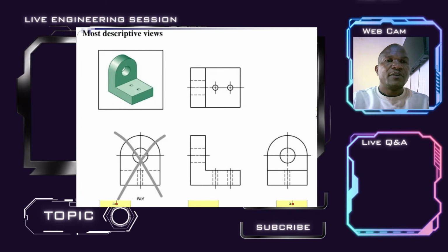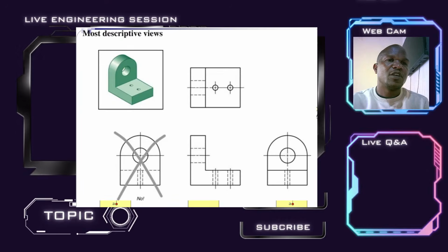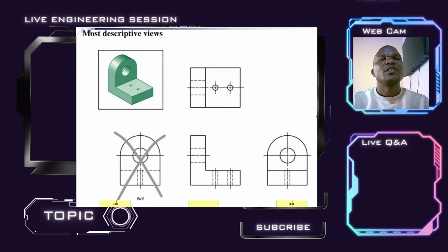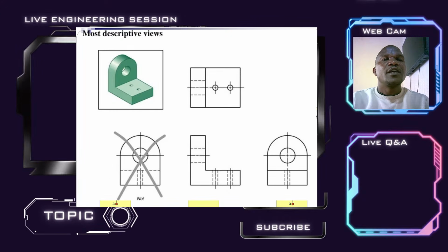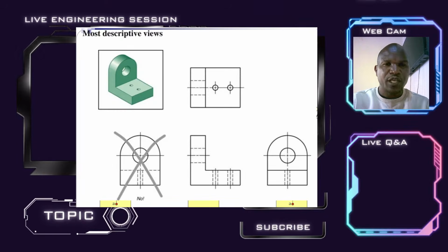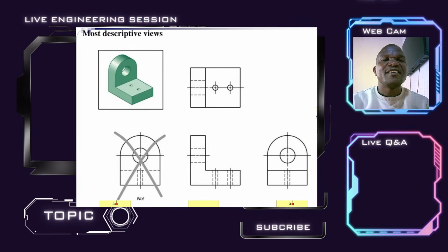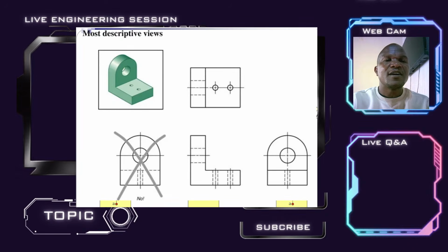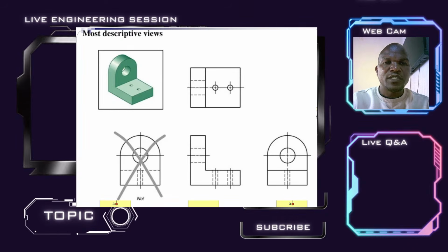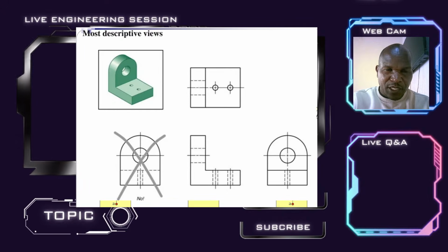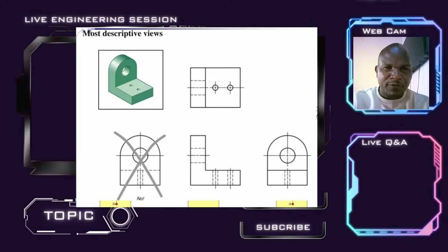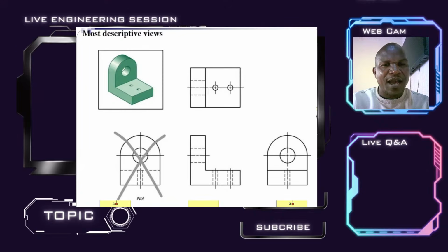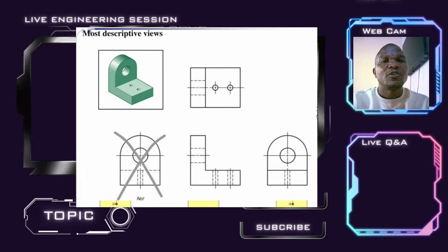Yes. Now, there's a good example. I have an isometric block, in 3D, on the upper left corner here. And there are the multiviews benefit. Now, I have cancelled one of the views, which is the same as the side view. And pay attention to this, what I was just explaining. The two holes from the front view cannot be visible. They coincide with each other, and therefore the inner lines are only 2, not 2 holes.